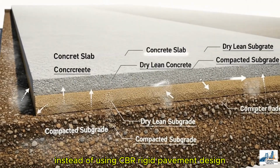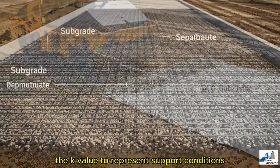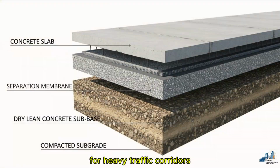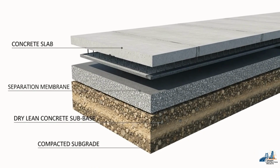Instead of using CBR, rigid pavement design relies on the modulus of subgrade reaction, the K value, to represent support conditions. For heavy traffic corridors, dry lean concrete sub-base layers are widely adopted to provide uniform support and prevent pumping.